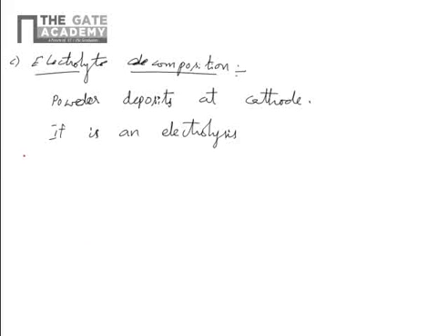We are not entirely discussing the whole process, because in electrolysis we know that an anode and a cathode will be there. You can keep both anode and cathode as a metal piece, or you can keep the anode as a metal piece, because most of the material ions pass from anode to cathode compared to cathode to anode. So if you want to create steel metal powder, keep the steel rod as an anode, and you can keep a steel rod as cathode also to get more metal powder.